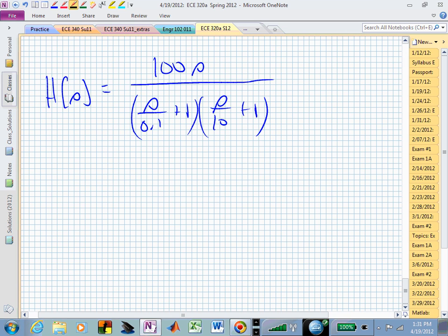What's the DC gain of this transfer function? 0. This one you can evaluate, can't you? You can plug s equal to 0 and you have a DC gain of 0. So this is going to annihilate constants. You put in a constant and it's not going to get out to the output. That's what that means, right? You're filtering DC dramatically. You have a DC gain of 0. But you do have this piece that will amplify all frequencies.